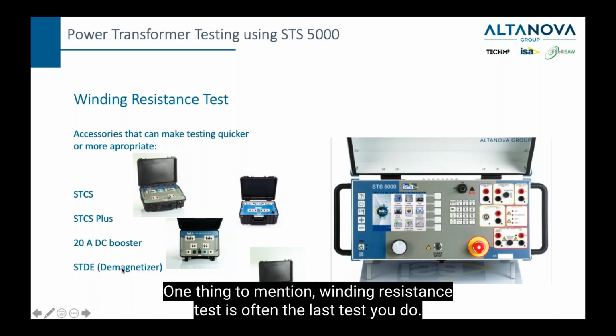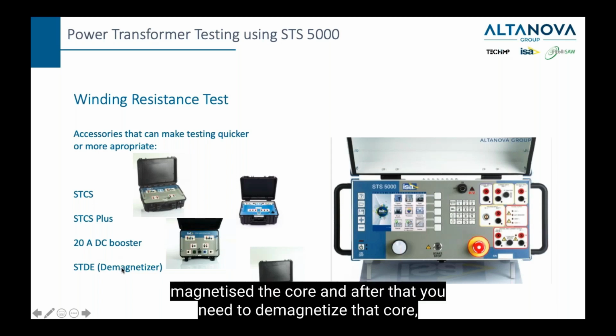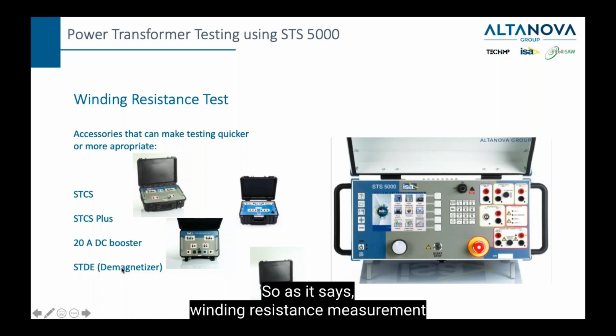One thing to mention, winding resistance test is often the last test you do. It is the last test you do because you magnetize the core, and after that, you need to demagnetize that core. Otherwise, you might have issues. But let's go back to the winding resistance test. So as it says,